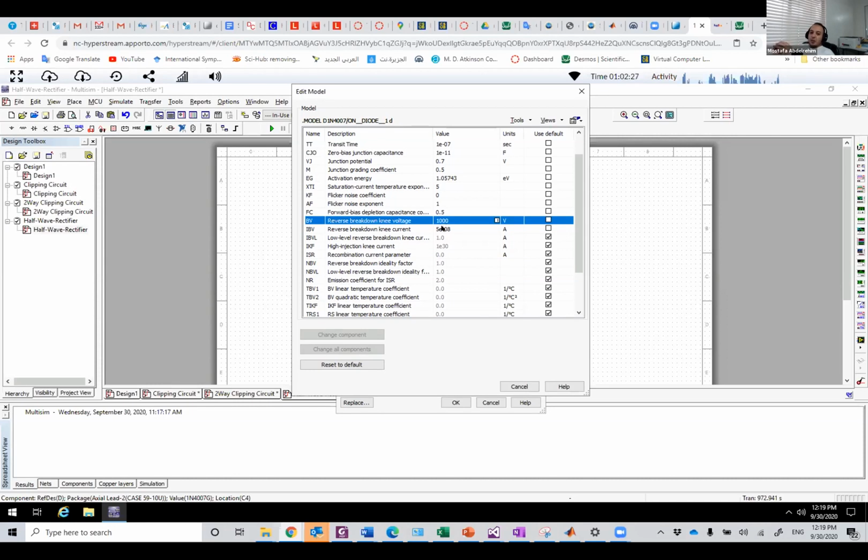That's why this is called a rectifying diode. When we use a rectifying diode, we usually neglect what's happening in the negative half cycle. We usually assume that the maximum negative voltage is always less than the breakdown voltage. But if this diode is very expensive, you must take that into consideration. So let's change this value.